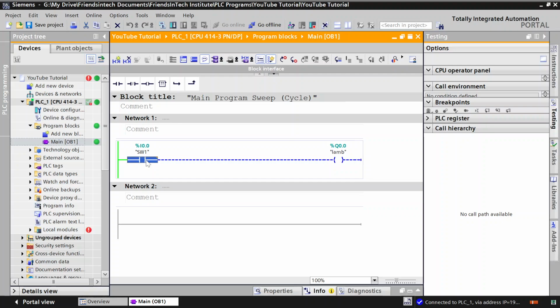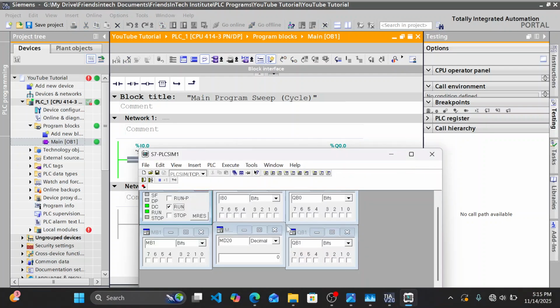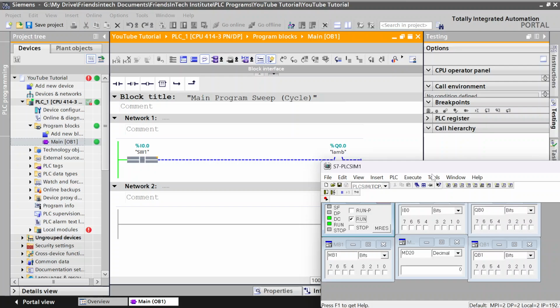Once an object is detected, it will change the state from normally open to normally closed. That is what's happening here. So you can change this here. And you see the power is flowing from left to right. In ladder diagrams, another convention is that when reading a ladder diagram, you start from the left-hand side to the right.